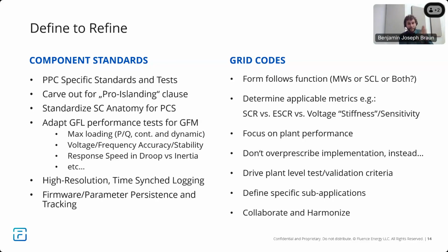But what we need is the immediate response, which would come from the physics of a synchronous machine. So if you show a voltage event here, and within 5 milliseconds or even earlier I see a change in your current, great. That means you're grid forming. That's at least the first hurdle.